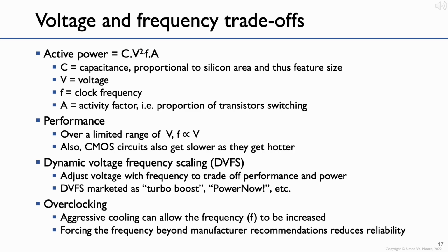Still, aggressive cooling will make your device go faster because it can operate at a higher frequency for longer. And the final note is, operating the frequency of a chip beyond its manufactured recommendations will start hitting reliability. And it's actually quite complicated how you work that out, when you're going to see reliability problems. So, yes, basically beware if you want to get into overclocking.